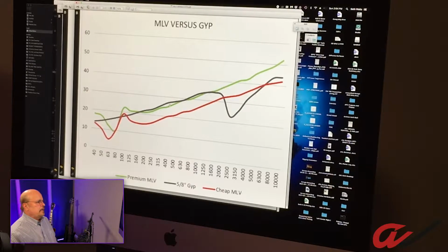But this is a free hanging sample. This is tested in the lab, free hanging in an open space with an airtight envelope. Same thing with JIP. So you've got these conditions that aren't the real world. These aren't the way you build things. So if you take MLV and you sandwich it in between a couple of things, or even you put a layer of drywall over it, it's contacting the MLV, you're not going to get this free field performance.